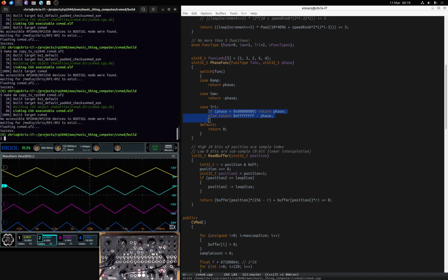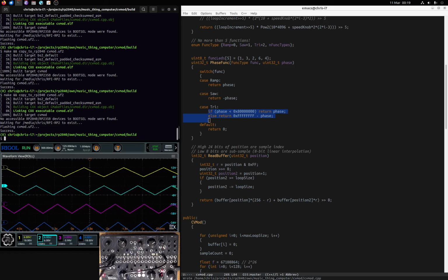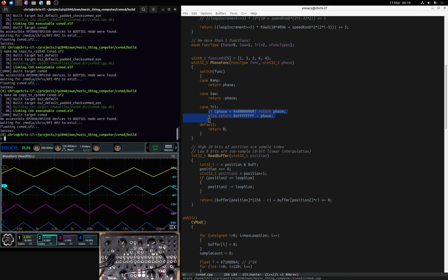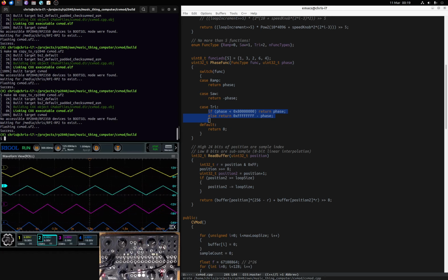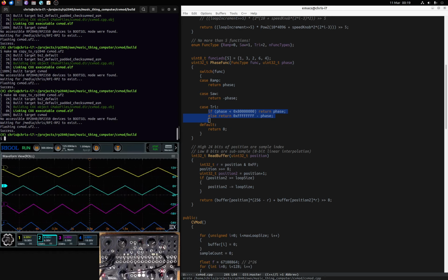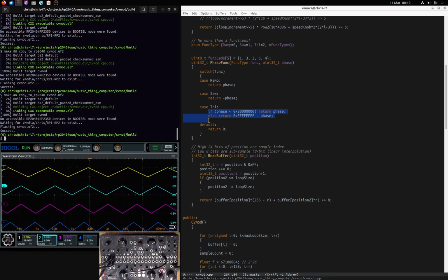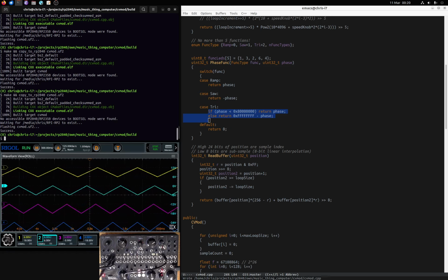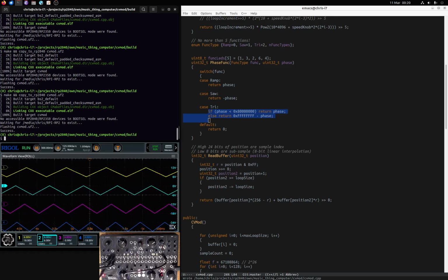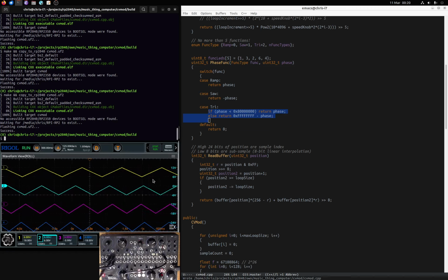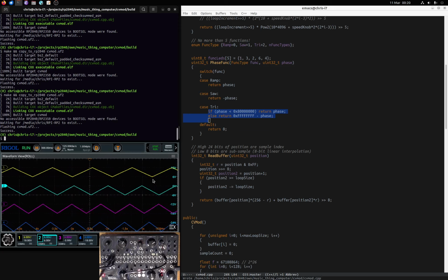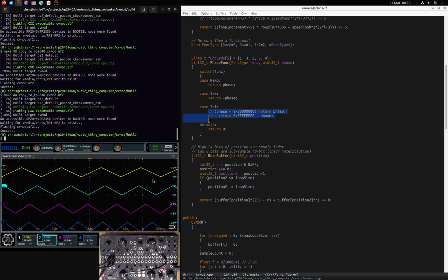And here that's fine, but all of these signals are negative. And I think this is the correct thing to do for the playhead phase, because it's the thing that minimises the glitches as the playback heads cross over the record heads. I think they only do that once per cycle at the extremum of one of these triangle waves, at one of the changes over, which I think is about the best you can do.